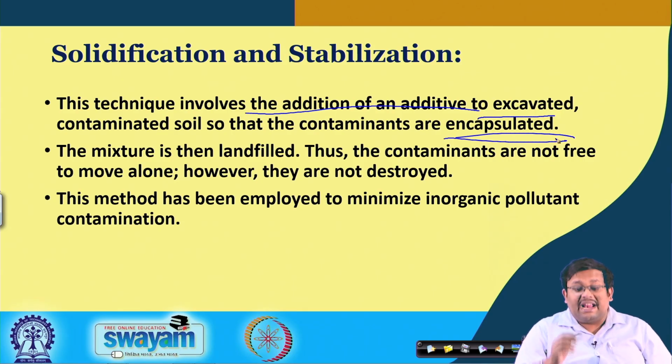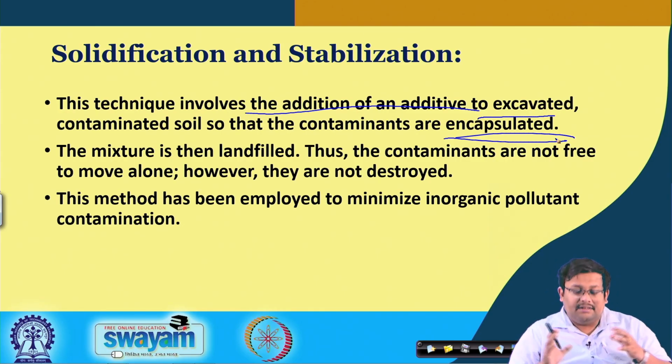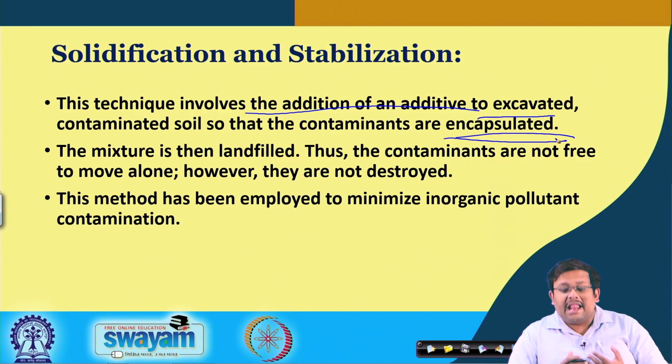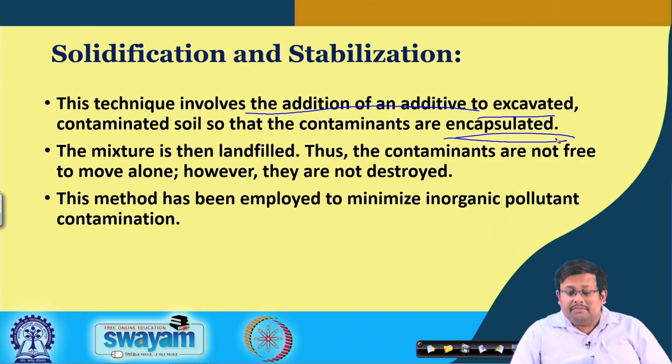The mixture is then landfilled, so the contaminants are not free to move along; however, they are not destroyed. They are contained in the landfill region after being encapsulated with the help of these additives. However, this method has been employed to minimize inorganic pollutant contamination in some places.